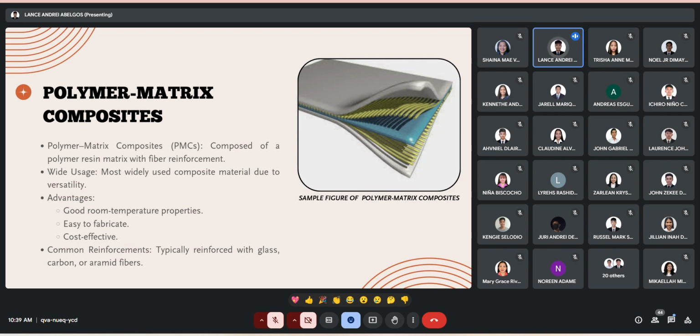The polymer matrix binds and supports the fibers, allowing for an efficient load transfer and adding durability to the composite. And it is widely used in various industries for their high strength to weight ratio, durability, and resistance to corrosion. These composites are valuable in applications requiring lightweight materials such as aerospace, automotive, sports equipment, and infrastructure.